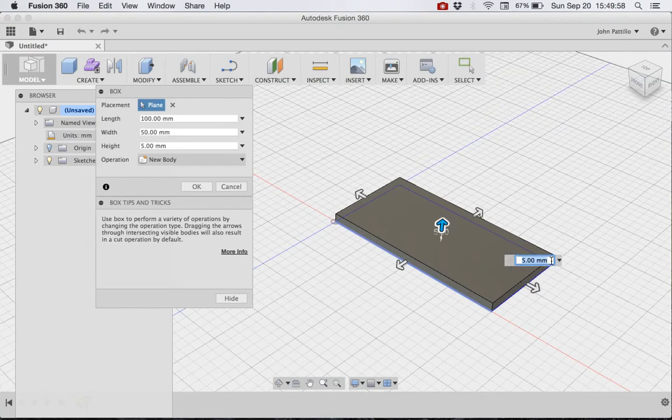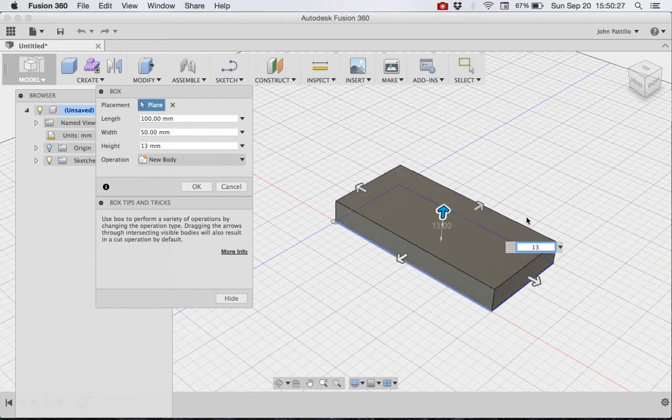Okay. Now the z-axis is where you have to think about it a little bit. I'm using Baltic birch plywood, which is 12 millimeters thick, and I'm going to glue a 2 millimeter sawn veneer onto that. So the total thickness to start with is going to be 14 millimeters. And then I want the x-carve to mill off 1 millimeter. So my final piece will end up being 13 millimeters thick. So that's what I'm doing. I'm building a model of my final piece.